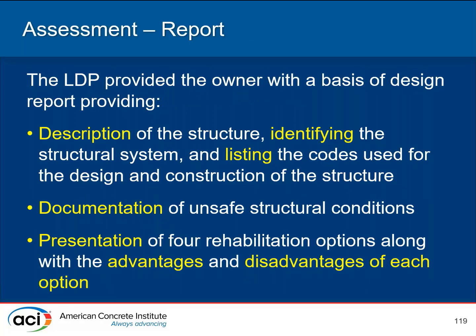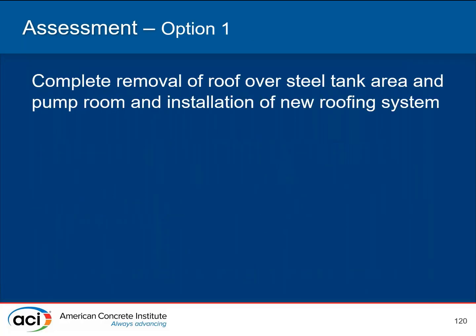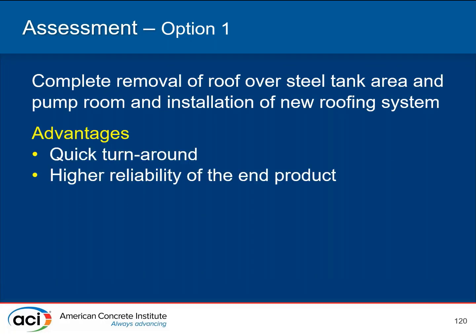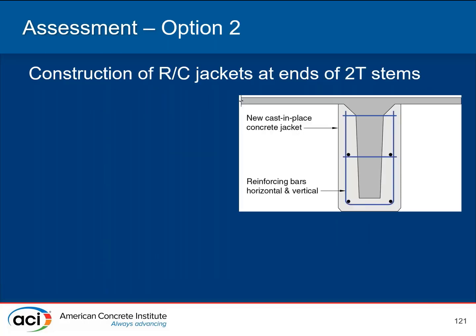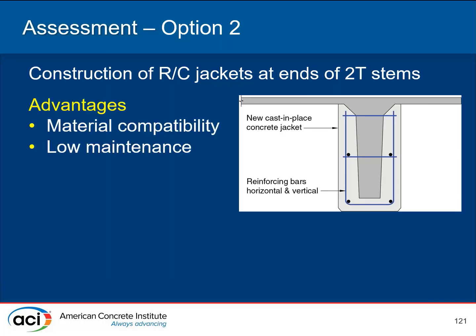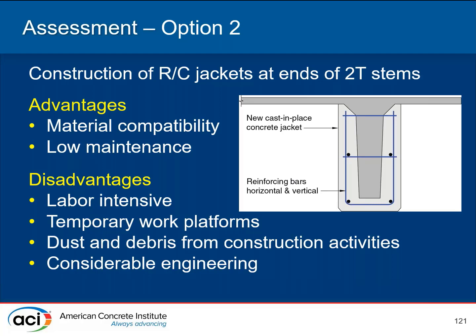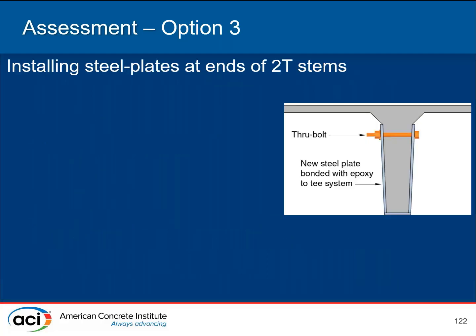Provided them with a report describing everything and looked at 4 different options. One of them, removal and replacement. Quick turnaround, really costly, but very disruptive. Looked at reinforced concrete jackets. Good compatibility, maintenance is low, but very labor intensive, very disruptive. A lot of dust and debris, going to be a big problem.